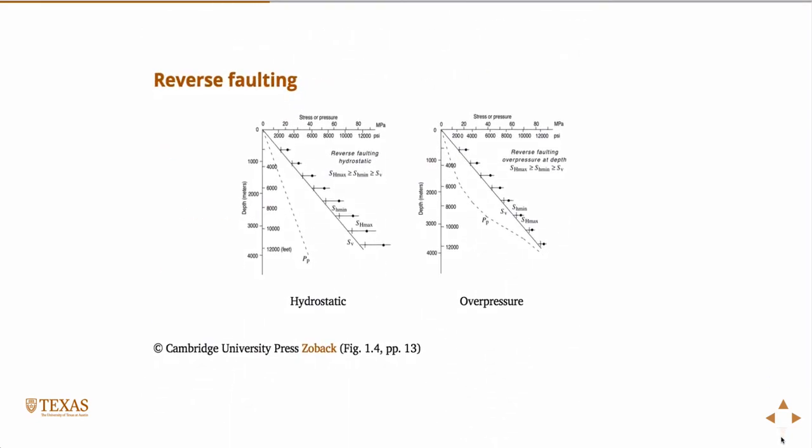Reverse faulting. In a reverse faulting regime, what's the vertical stress in terms of the other two? It's the smallest, right? It's the least, right? So we still draw it, but now the other two are to the right side, okay? And you still see some effect when you go into an overpressure scenario, that the distance between these two will be squeezed down, and that has to do with the effect that the pore pressure plays. Okay, and we'll see that when we start actually talking about the constituent models for these guys.